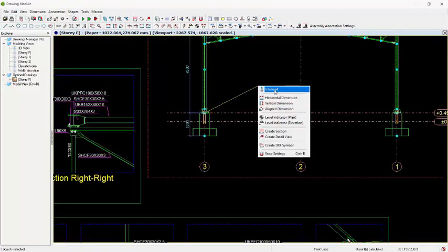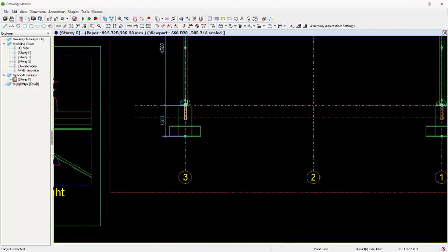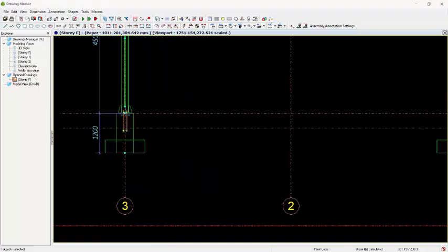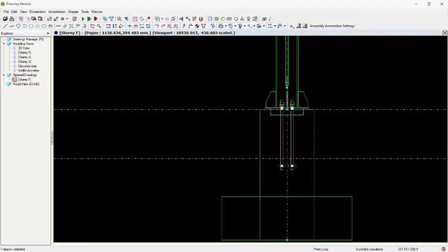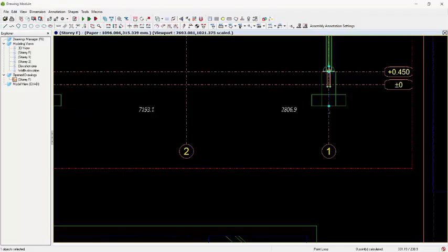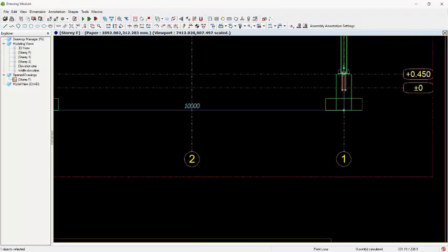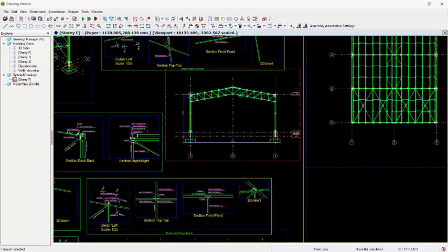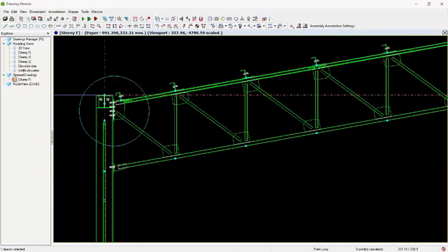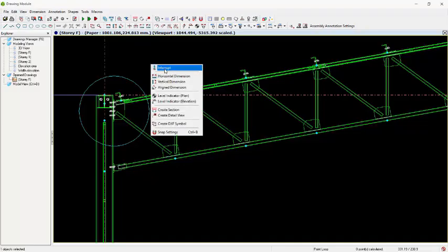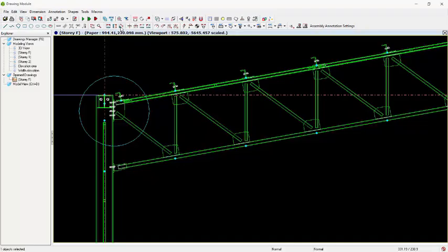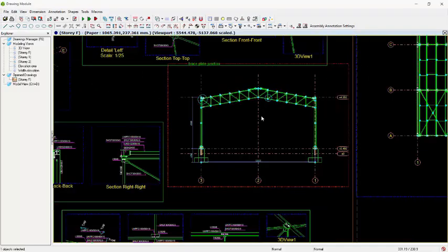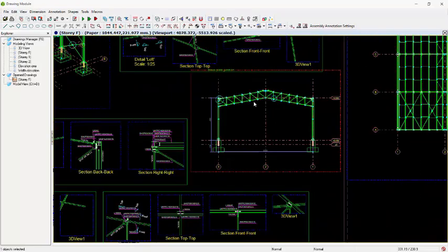This is horizontal, so you interrupt and pick the horizontal dimension too. Pick that point, come all the way to this point, pick that. Then you right click right there to have 10 meters spanning in that direction. Also, if you want to make an angular dimensioning, you can use this for angular dimensioning successfully. So this is how all of this is used.